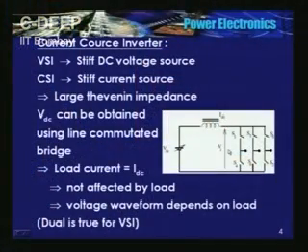A load commutated inverter fed synchronous motor drive is nothing but a current source inverter with 6 SCRs feeding a synchronous machine or synchronous motor, wherein the power factor is leading. It is quite attractive.